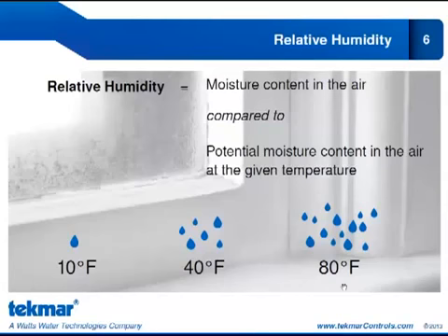And if we increase the air temperature again to 80, that same amount of water could be 10% relative humidity now. So it does change with air temperature, and that's because the warmer the air is, the more thermal energy that is available to evaporate the water molecules.